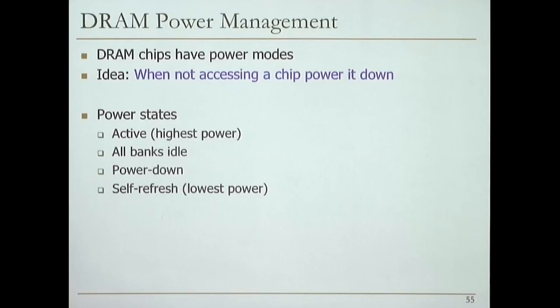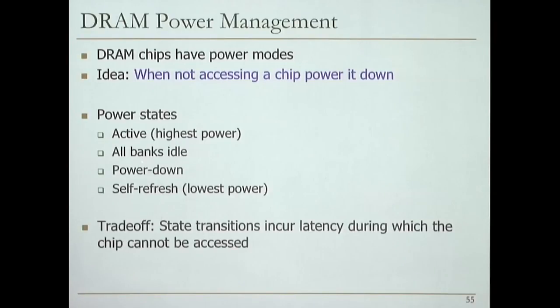Now there are trade-offs, of course. Transitioning between these different states incurs latency, because you're powering down or powering up components, and that takes time. During these state transitions, you cannot access either the entire chip or parts of a chip. For example, if you want to go into self-refresh mode, it takes some time, but you have the lowest power, since you're only doing refreshing. But getting out of self-refresh mode takes even longer.